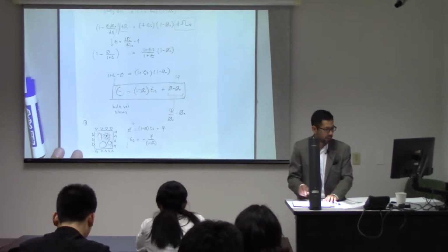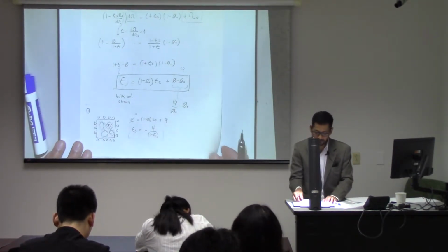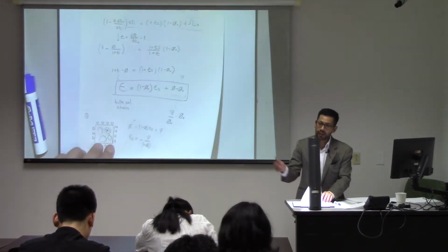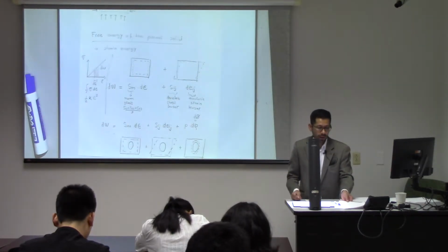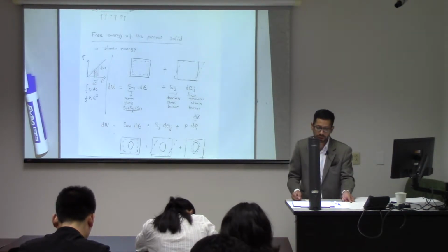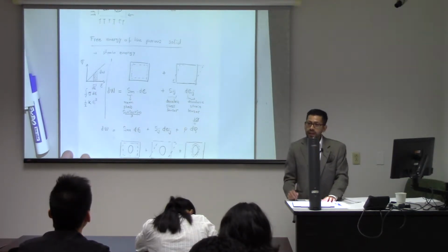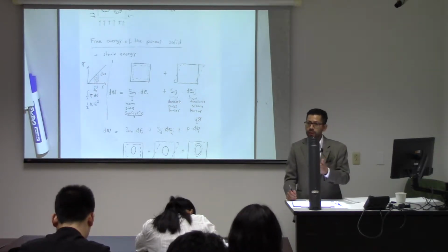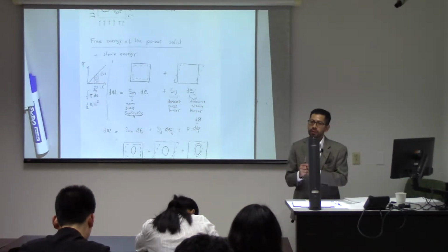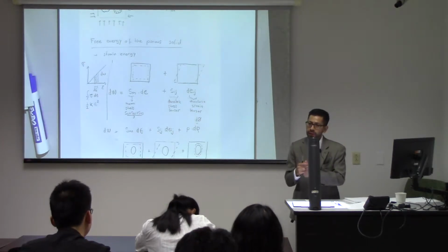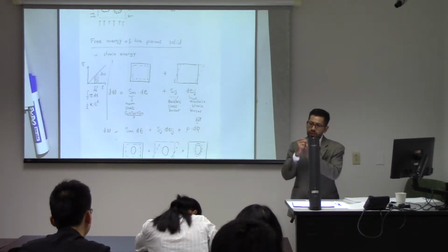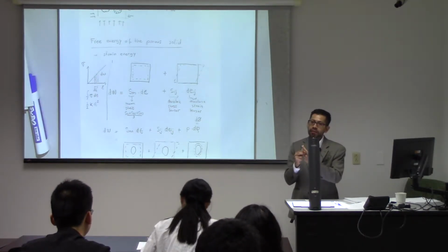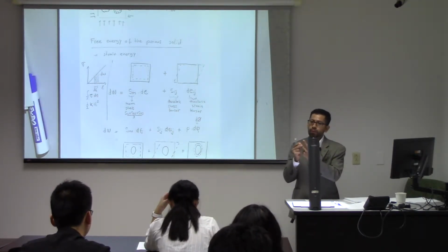And we worked through some examples of what is a solid strain and what is a porosity strain, and how you can change those two according to the boundary conditions. So very important now, remember that before, just for solid mechanics, we had two types of boundary conditions: displacement constraints, stress prescribed, and also now we have a third one, which is pore pressure.